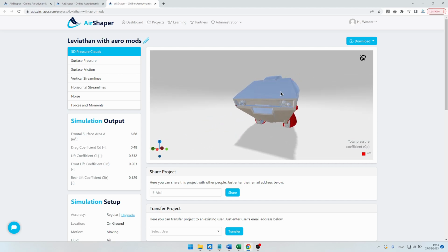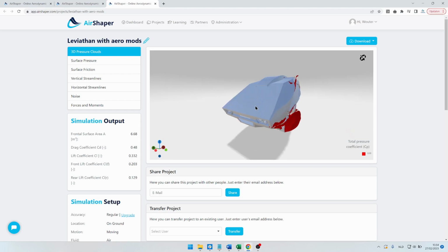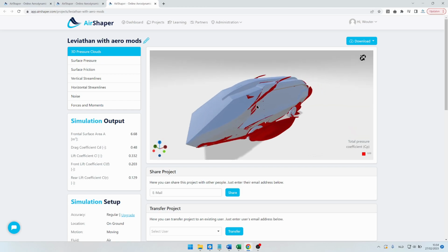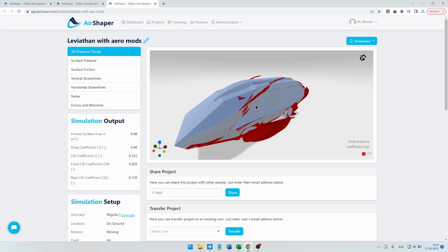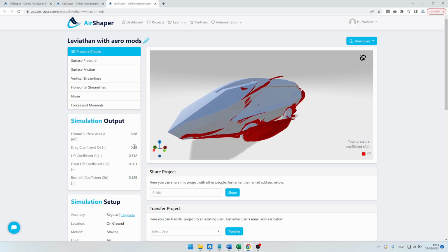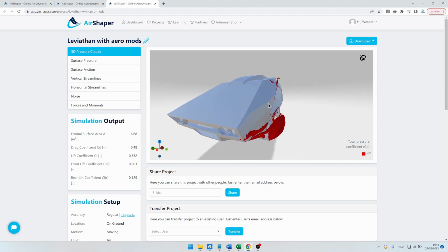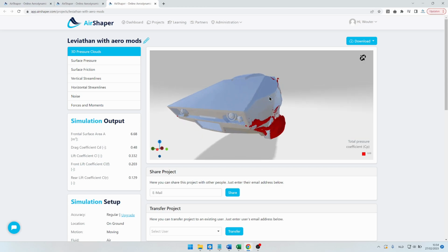That's actually something you will notice in terms of range. Because aerodynamics at high speeds can be responsible for over 50%, sometimes even 70% of your fuel or battery energy consumption. So reducing it by 4% might actually increase your range by perhaps 2% or even more. So that's really relevant, especially if you can do it with some small changes that don't really cost you anything.